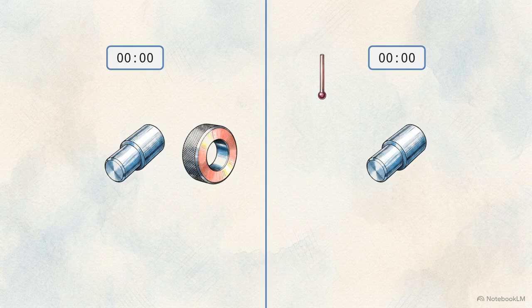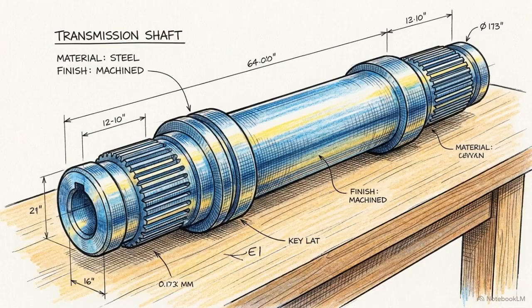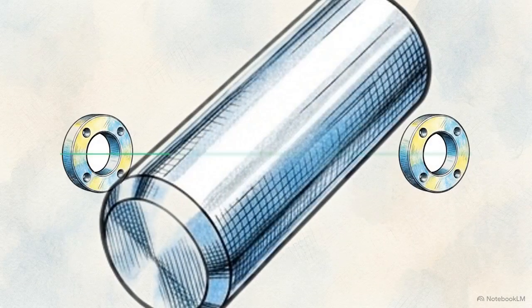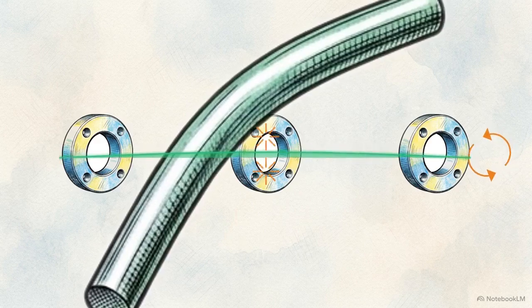Dragging a leader line to a surface profile versus snapping it under a dimension takes the same amount of effort in CAD. Yet that choice determines whether the factory uses a high-speed manual gauge or a precision CMM for every part produced. Axis straightness is a clear call for long components. If a drive shaft must pass through multiple bearing journals, controlling the bend of that axis prevents the shaft from binding as it spins. This cheat sheet tracks the most common drafting errors.